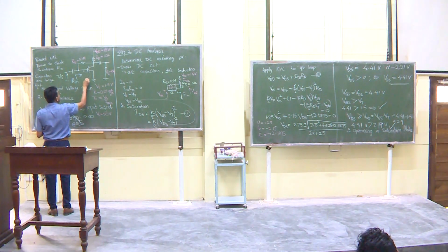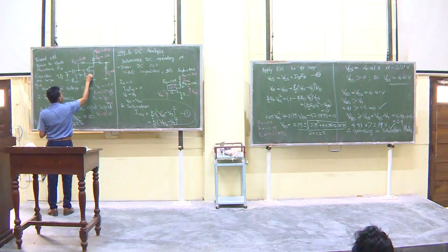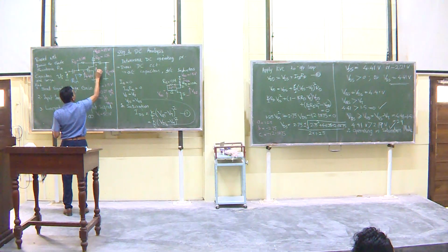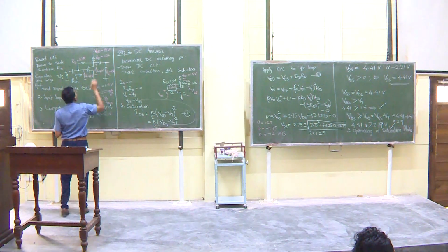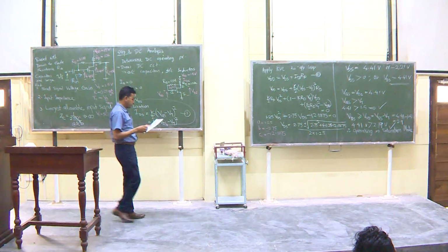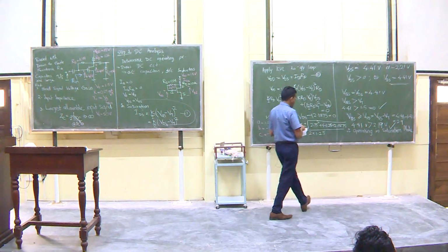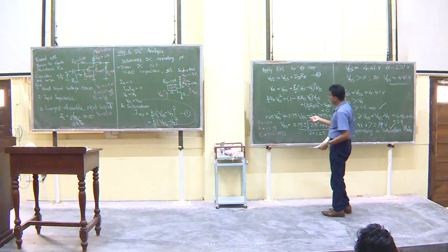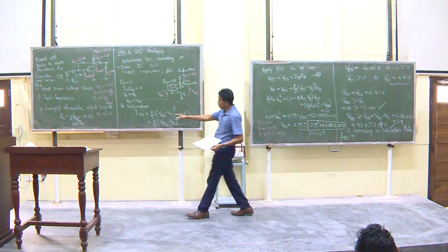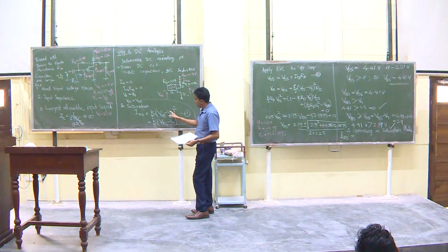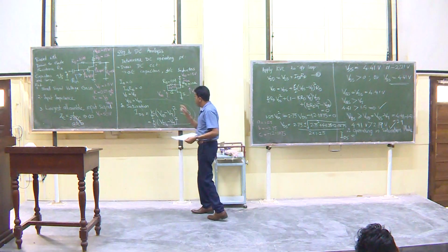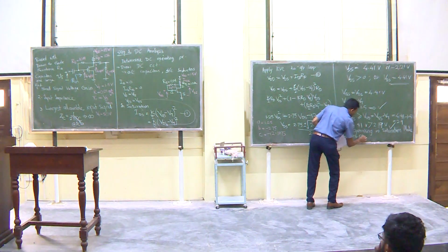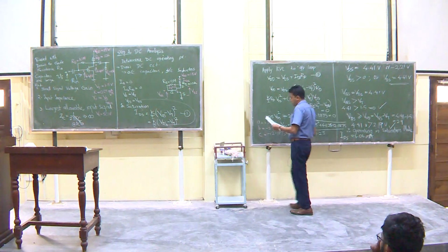Okay. So, we know the Q point. This voltage is 4.41 volts, which is the same as this. If you want, you can find the ID also. IDS is equal to, using the equation you applied, VGS minus VT is 2.9, 2.9 squared times this, you will have this equal to 1.06 milliamperes, right.